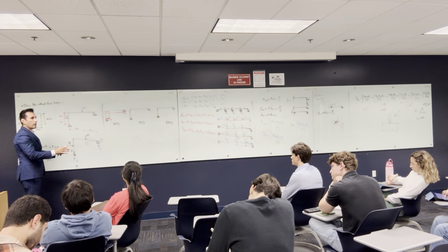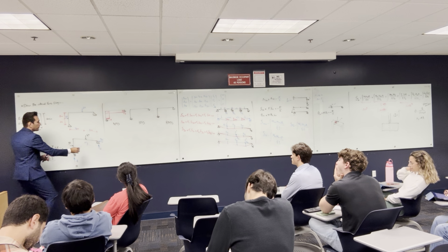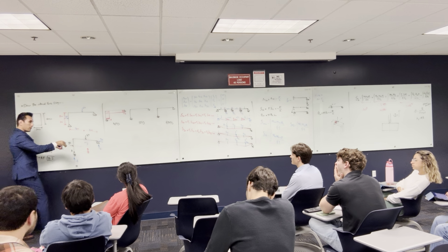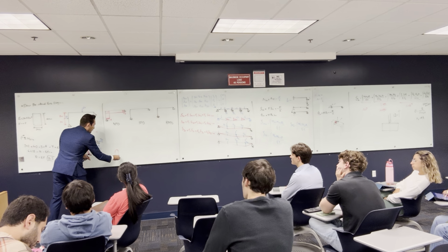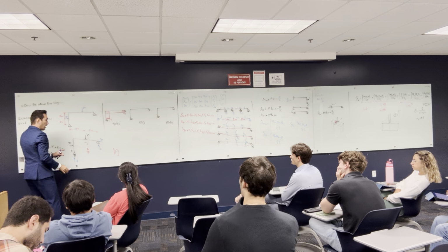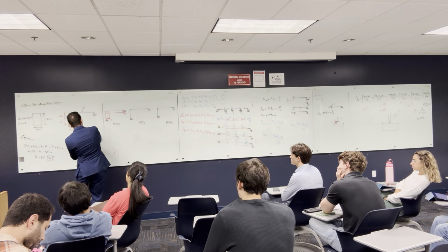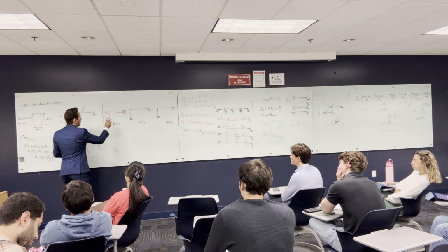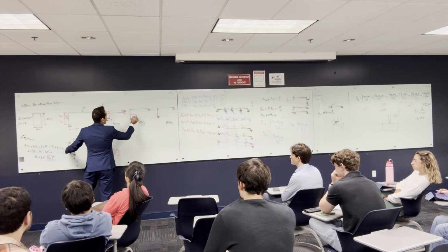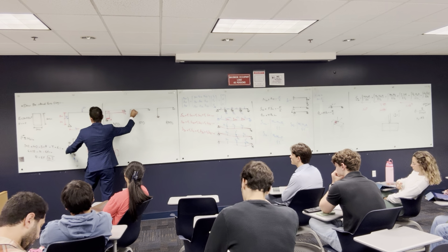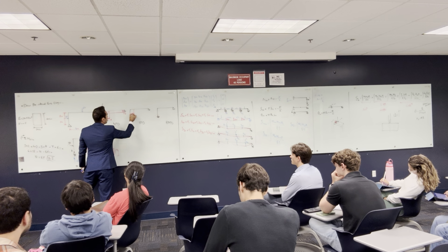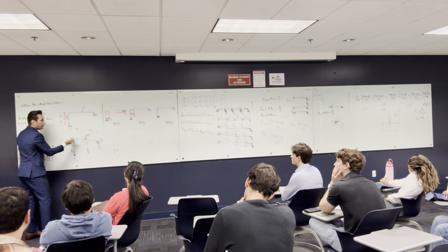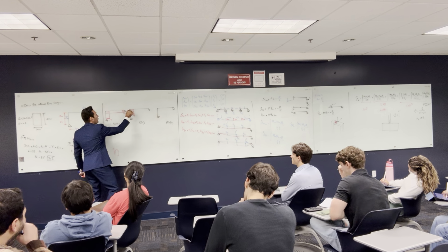And the thing is, like the convention, the sign convention, you put yourself here inside the frame, right? And you look, here's the cross section. If the shear force is going up, it's gonna be positive. If it's going down, it's gonna be negative. So I'm here, and the shear force is going down this way, so this shear force is negative. It's gonna be -3, something like this, and it's gonna be all the way up because there's no other force. So this is -3. All right, how about here? Here you have a 4 going up, so that means it's positive. So I'm gonna go 4.